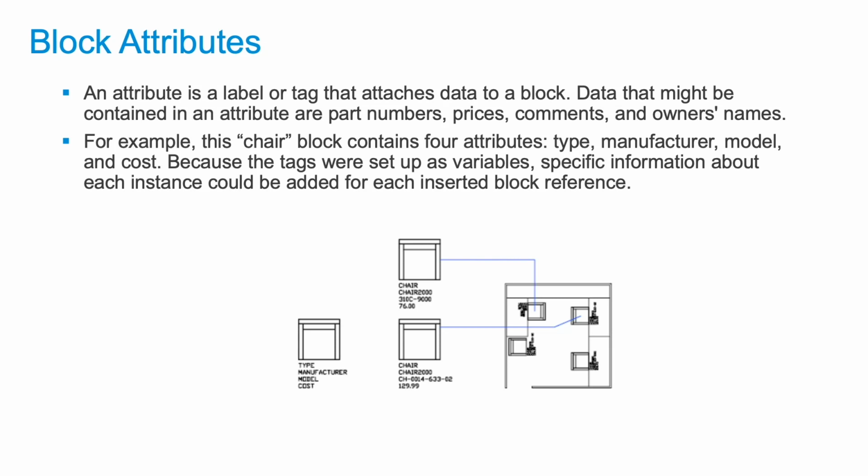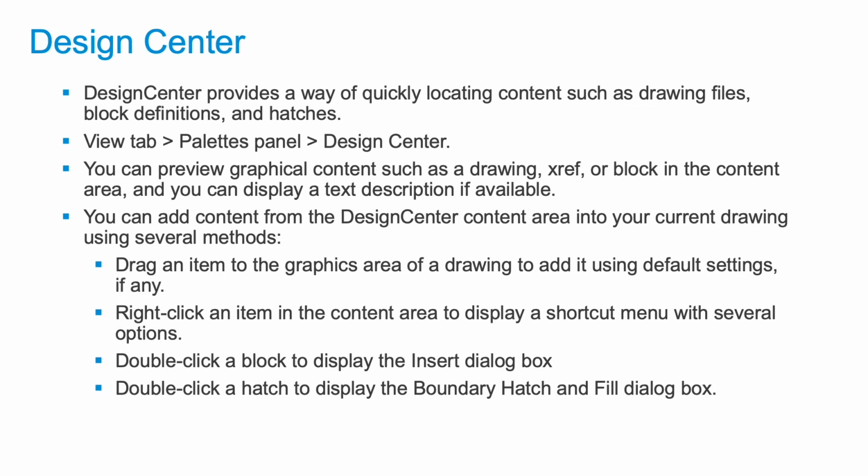AutoCAD allows you to create tool palettes that link to your blocks to make it easier for you to access and use the desired content. If you use a tool palette to access your blocks, it's important to understand that the palette is linking to the external block files. If those files are moved or deleted, the block tools on the palette will no longer work. For this reason, many users prefer to use the Autodesk Design Center. They use the Autodesk Design Center to bring blocks into their active drawing.